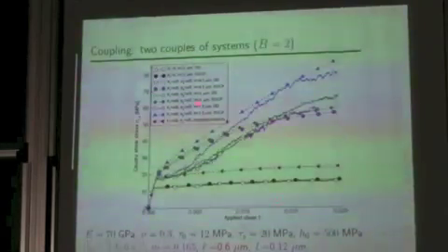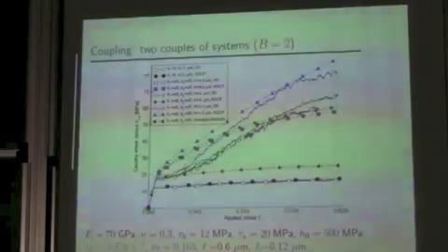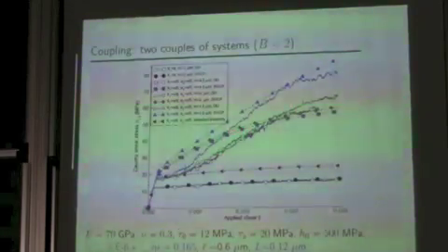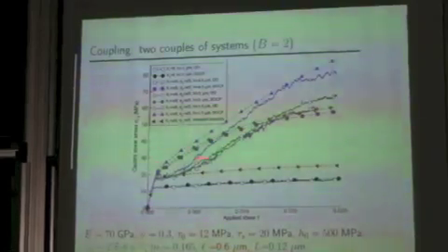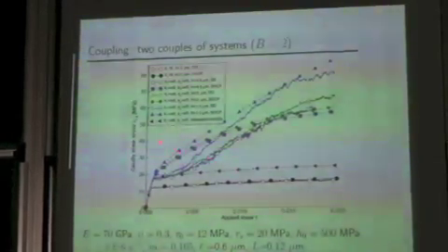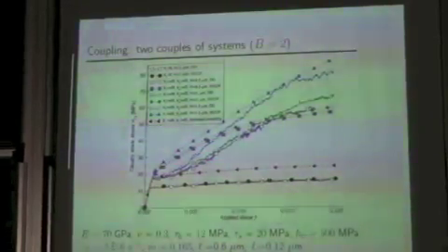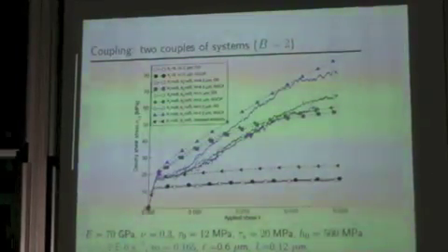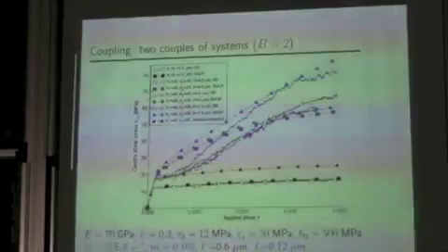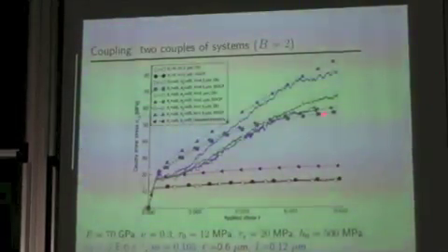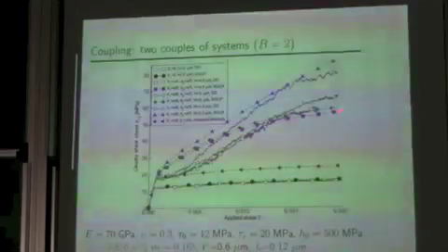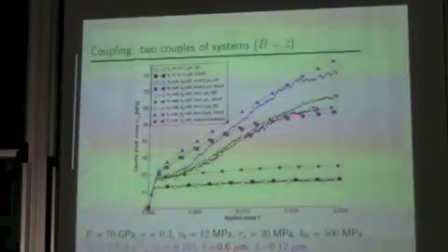If we look at the case with two couples of slip systems, the comparison is pointwise worse, of course, but globally it's not too bad. The problem just after the yield stress is worse, but at least let me notice there is a quite nice thing that strain gradient crystal plasticity seems to predict, and this is a sort of exhaustion of the size effect.